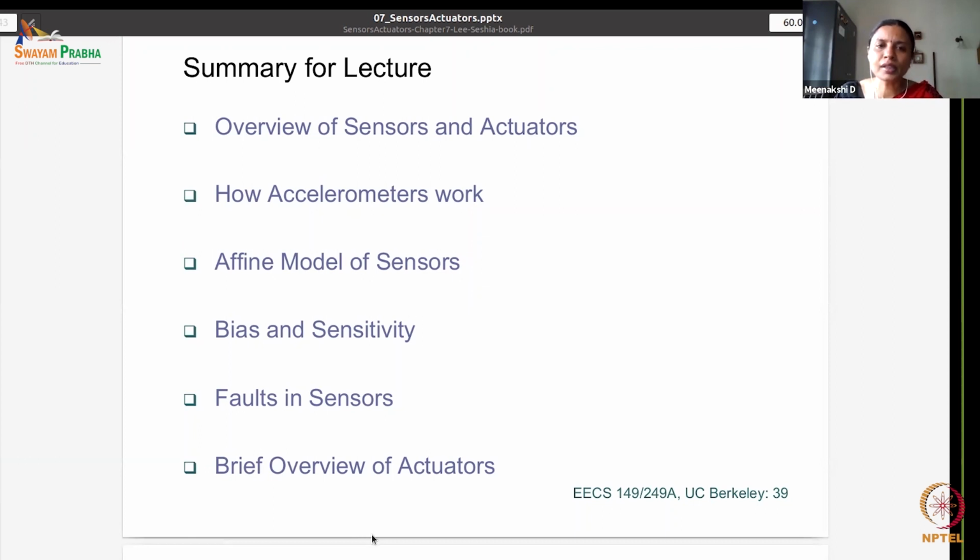In serial interfaces, for example, if you take RS-232, it supports what we call an asynchronous serial connection, where the hardware clock is not common. RS-232 is replaced by USB, which is simpler but has a more complex protocol, or Bluetooth, which is completely wireless. Similarly, you have a UART, a universal asynchronous receiver transmitter.